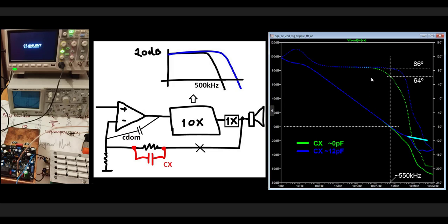Okay, and we have more phase margin. But we want to put this thing in the limit. Reduce this capacitor, go up with this gain to the maximum possible, because we need to have gain at low frequency to attenuate internal perturbation.